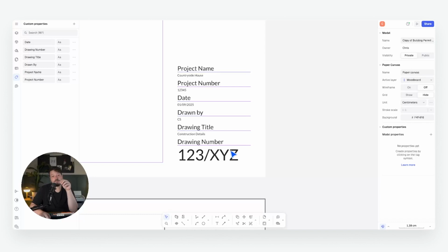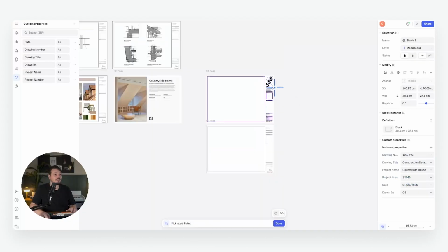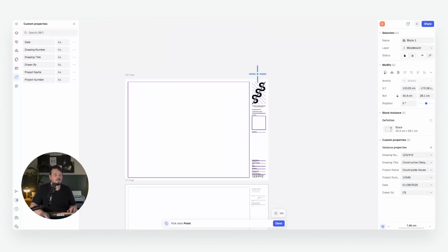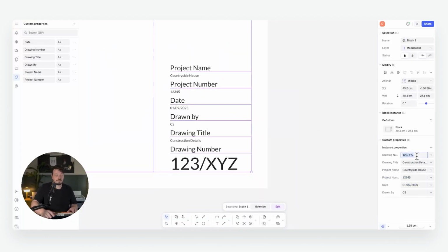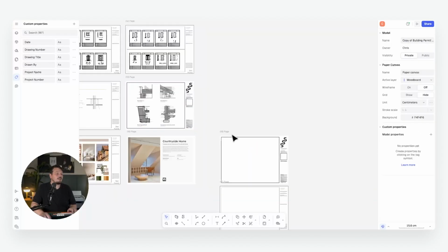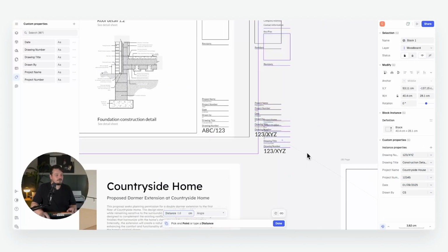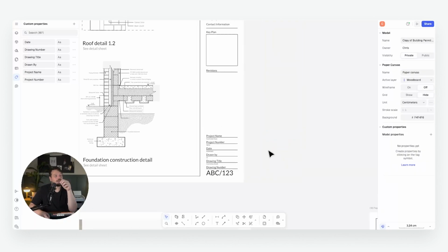And that means that if I was to then copy this title sheet across, so say we'll get rid of that standard block and put my new title block in, I can change those parameters to ABC 1, 2, 3 and project number to 7, 8, 9, 10. And then if I just go back to there, you can see that my original has not changed. So basically that metadata allows those things to be edited, so you can fill in your block as and when you see fit.